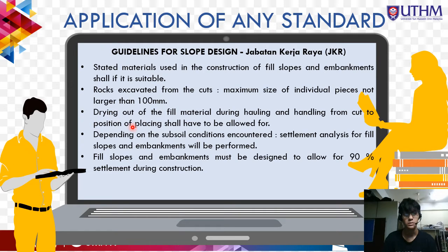Drying out of the fill material during hauling and handling from cut to position of placing shall have to be allowed for. Depending on the subsoil condition encountered, settlement analysis for fill slope and embankment will be performed. And lastly, fill slope and embankment must be designed to allow 90% of the settlement during construction.